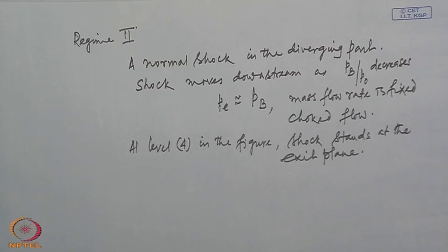And what happens then is that a supersonic Mach number exists everywhere in that uniform or constant area duct, and the flow becomes subsonic at the end of the constant area duct. This constant area duct can then be used as a supersonic wind tunnel. So, you see that back pressure level 4 is the maximum back pressure at which we can have a supersonic wind tunnel operate.